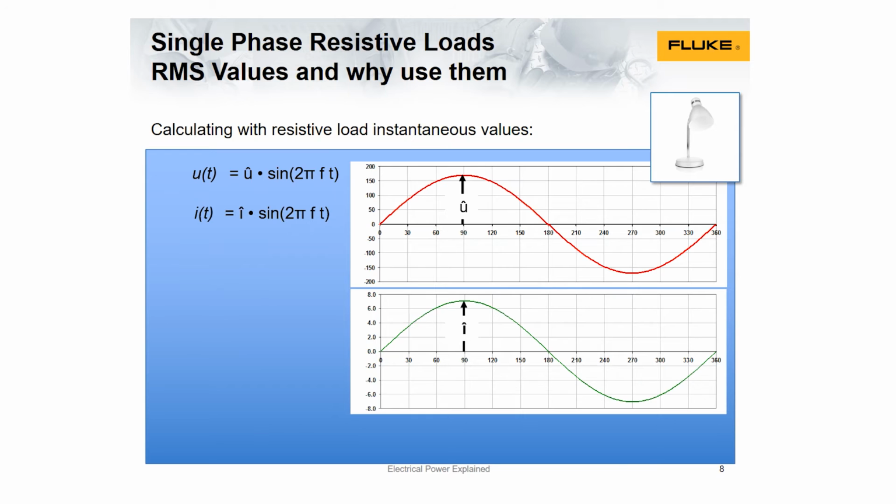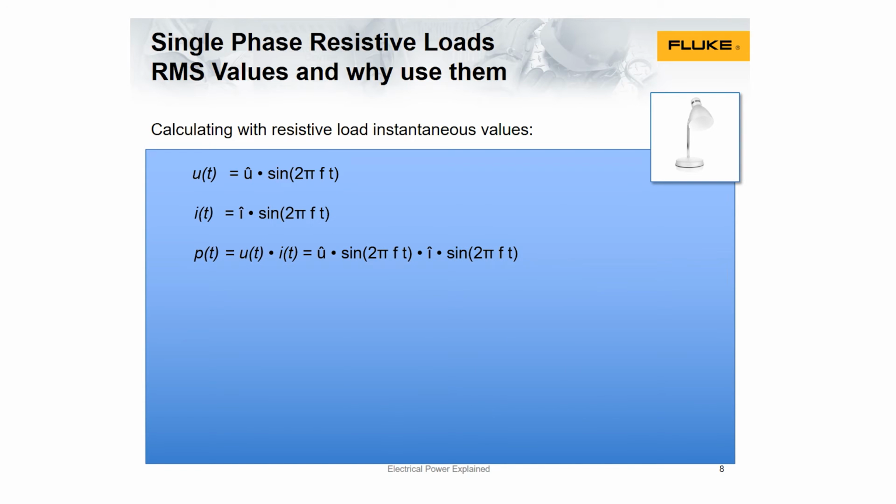Instantaneous power is, as before, P(t) equals U(t) times I(t), where P(t) is constantly fluctuating. We now need a single figure to represent the average power that this varying voltage can deliver into a load to correspond with or develop the same heat as a DC power P. The average value of the instantaneous power P(t), similarly, has parameter value P.